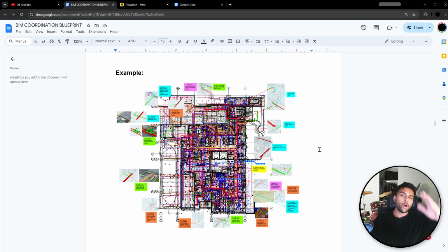In order to do this, you'd have to open the hydraulics models and see how far away from the soffit the hydraulics model is, what the slope is, and then calculate when it's coming down, and then see what the height of the duct is. And then, okay, it's just nicking the end of that, so we have to lower the duct, or we have to... so it's a pain.